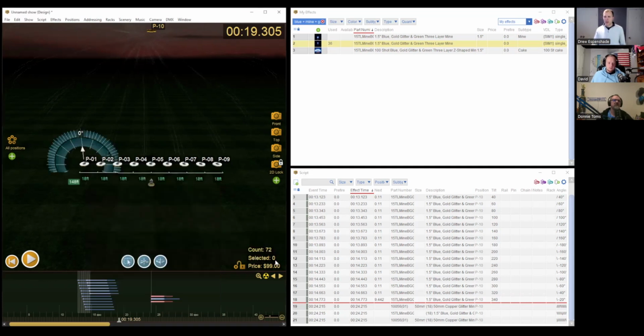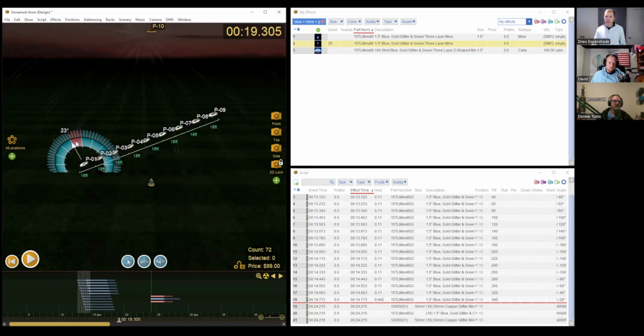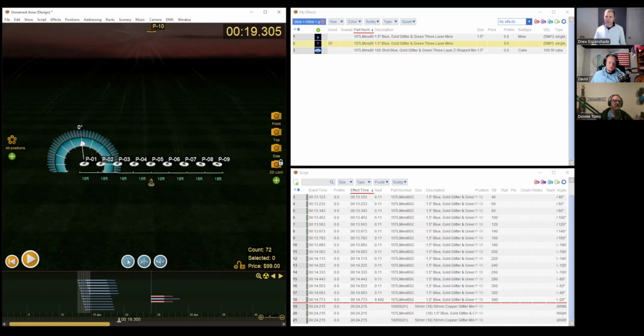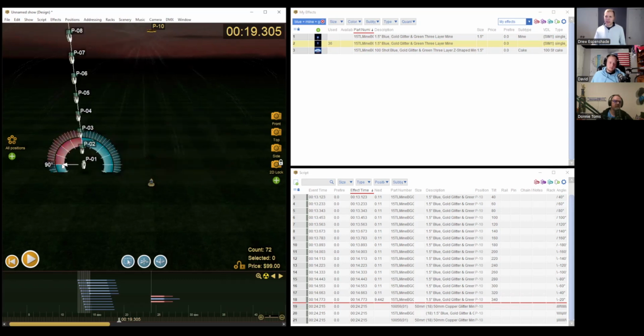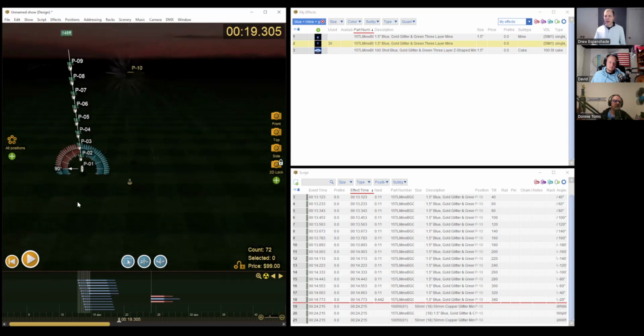So if we do that and choose roll, now we've got this dial we can grab. If we keep the arrow in here, we're going in larger increments. If we come out here, we've got 5-degree increments. If we come out here, we've got 1-degree increments, right? So that's what the dial is. What we really need is 90, so it's pretty easy in this case. So we'll just go over to snap it into 90, and there we go.